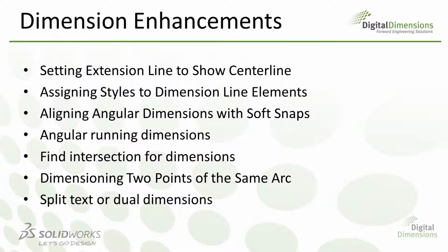Aside from just setting that extension line to show center lines, we can assign separate line styles to different dimension line elements. So if you've come from AutoCAD and you miss the ability to change the extension lines and the witness lines all to different line fonts, we now have that expanded ability to do that, including the ability to set that up in your document templates.